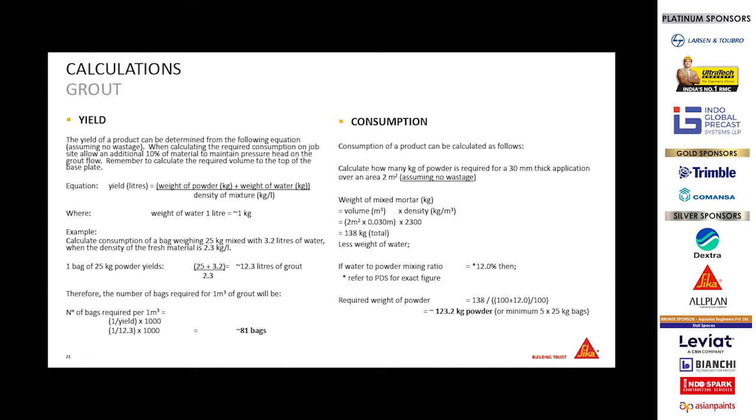In both cases, in case of less material, the waiting time is more. The grout material that you have partly used, which has been mixed, has crossed the pot life, and then again we are mixing. Or in some cases, excess material is mixed and it goes to waste.